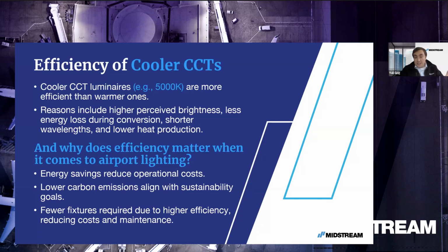So we were just there actually a few days ago, talking to them about what is the importance of efficiency compared to color temperature, and they have their own requirements there due to, I think, municipal codes. But what we were explaining is that if you have an area that needs a target lux level of, for example, 20 or 30 lux, with less efficiency on the luminaires, you need to firstly use more watts, 10 or 15% more watts, which means you're already using more energy, and so that's an energy loss. And secondly, of course, we convert that additional energy into CO2 equivalent.